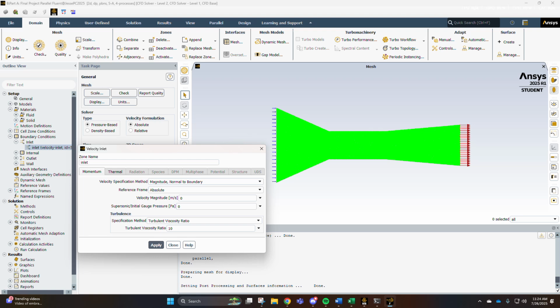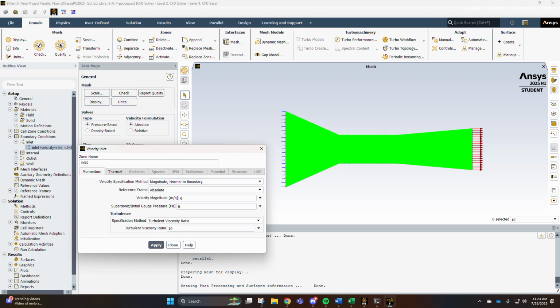Now, the project tells us to do a test velocity of 15 meters per second, which is for the test section. So our test section velocity has to be 15. So we have to do a little math using mass conservation. So we're going to use volumetric flow rate from the inlet to the outlet, and we were told to just use the height of it. So we're going to do 15 times 0.6096, then divided by 1.6256, and we get a velocity for the actual inlet of 5.625, and that should give us our 15 here, which was what we want.